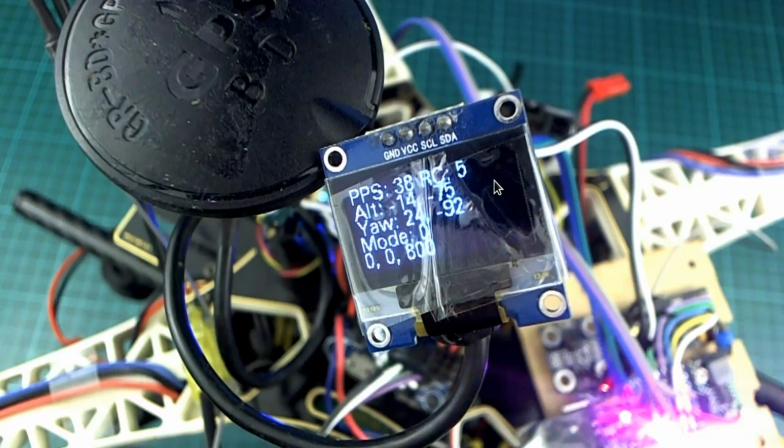when the follow me mode is engaged. So to do that, again, turn my radio on, and you can see the number 5 changing to 10 at the top, so I'm controlling the roll stick on my transmitter again. And if I turn my switches to the position where this follow me mode should be engaged, we'll see that mode number change to 1. So that is 1, obviously. That's just telling us that it thinks it's doing follow me right now. Of course, it's not going to get up and fly because it's not armed, and the flight controller is not in the right mode or anything like that.